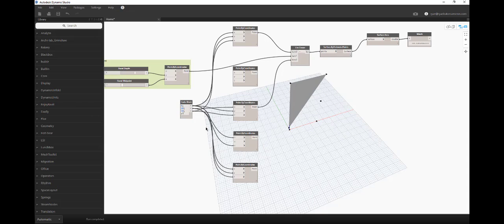X times -1, because I actually want this to go backwards at this Y. See, I didn't connect that point up yet. And there it goes. Okay, perfect. There, that's what I want. After I reconfigure this, as this goes forward, this one will go back, and as this one goes forward, this one will go back. So they have a parametric relationship. Wouldn't have to do that necessarily, but just for this example, let's go ahead and do it.